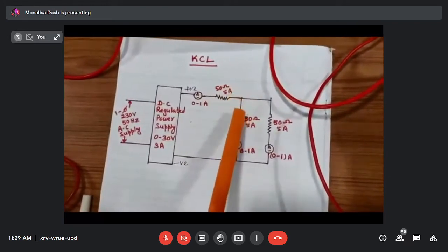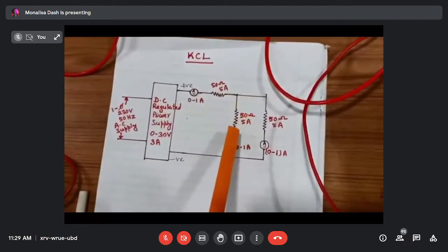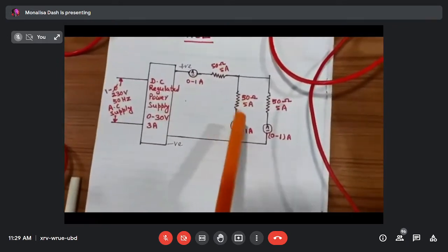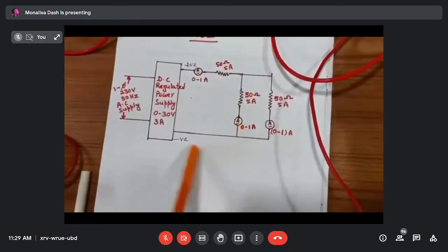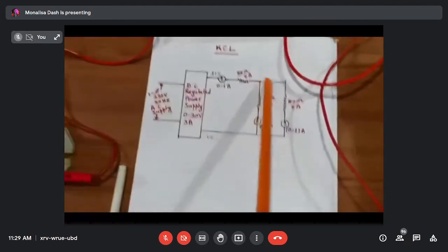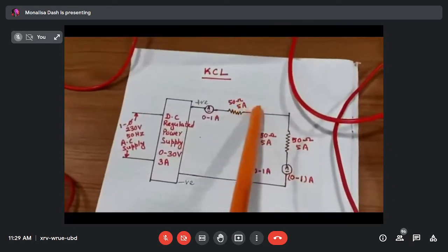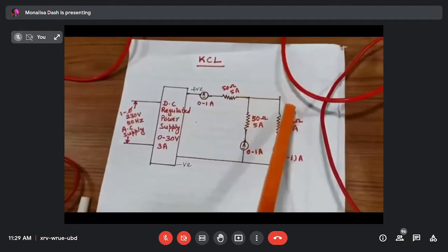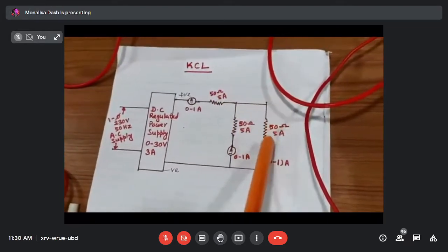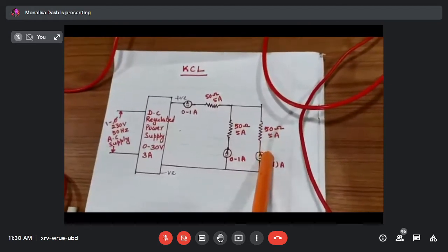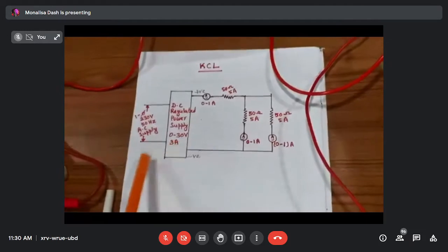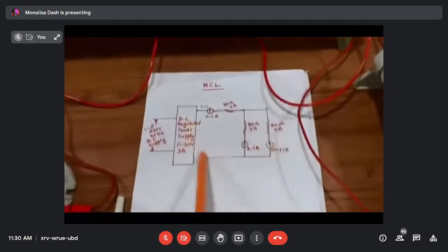end to one rheostat, then second end of the rheostat to ammeter, then ammeter range 0.1 ampere goes to negative. Then the rest of the circuit is the same: first rheostat second end to third rheostat first end, and third rheostat second end to ammeter common, the ammeter 1 ampere to negative. Our circuit diagram is over.